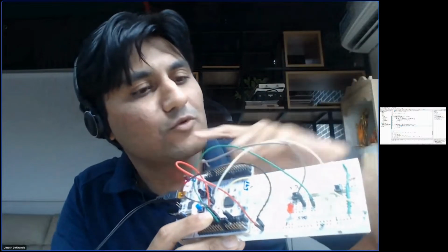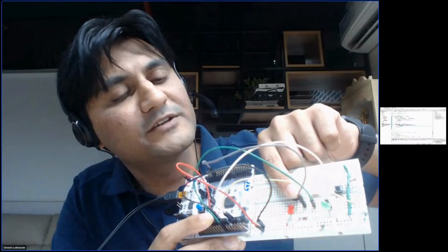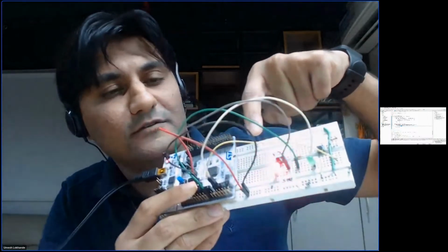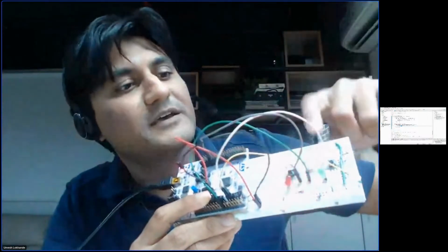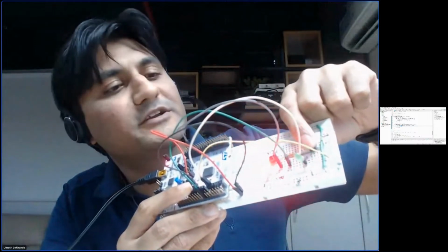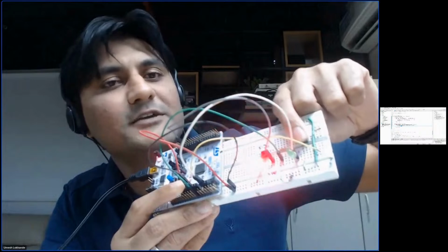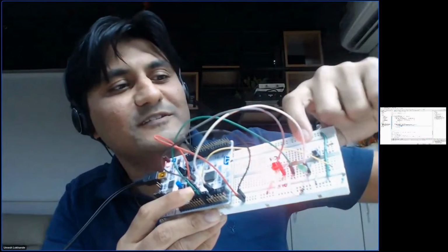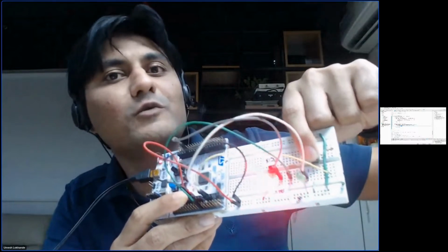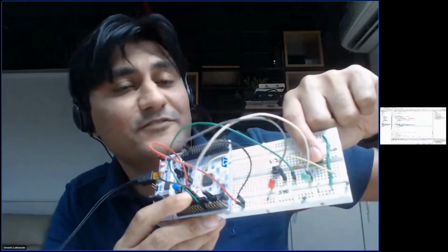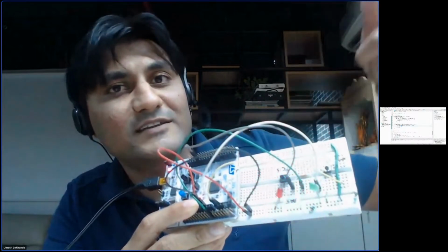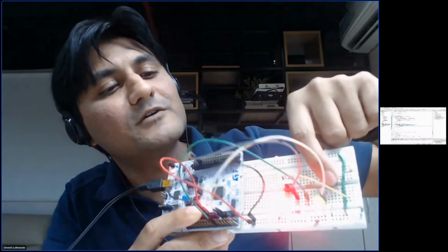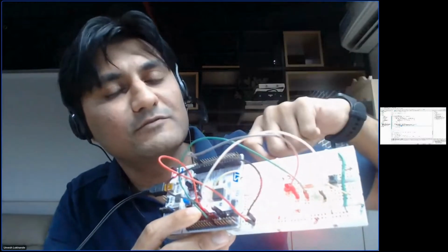And let me show you one more thing. Let me fire the high priority interrupt. If the high priority interrupt is working, so it's in the active state, and I press this button, the low priority interrupt, it doesn't matter for the rest of my life. If I keep pressing this button, this interrupt will not get fired, because the first button, this EXTI0, has a lower priority. That's why even if I fire this interrupt, it will not get activated until the high priority interrupt gets stopped. Once this interrupt stops, now only this will be working, right?